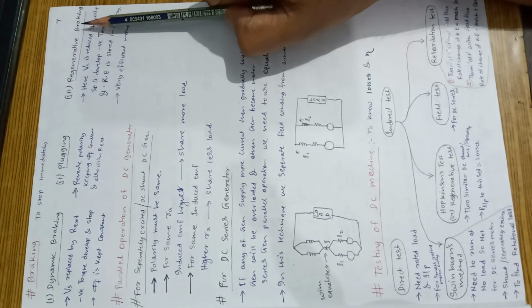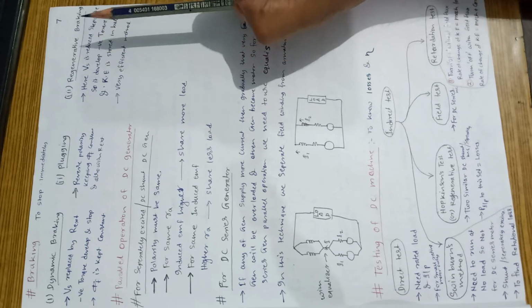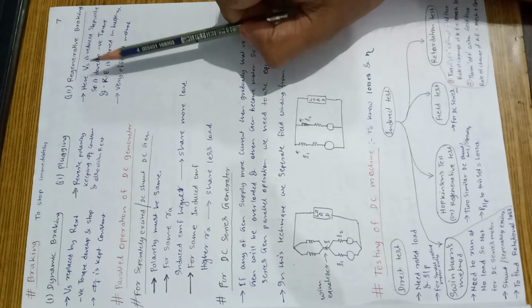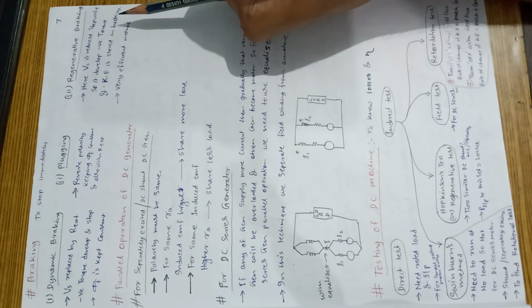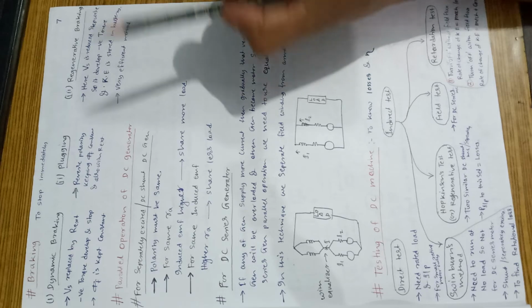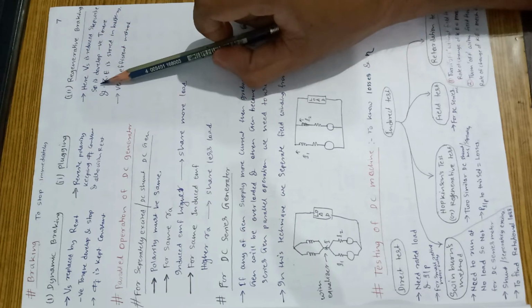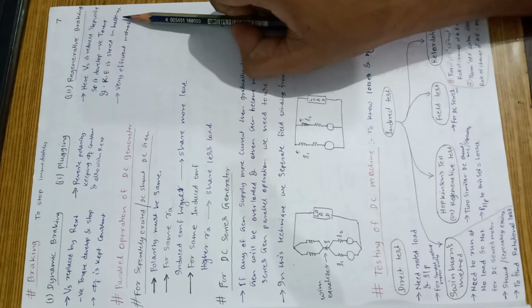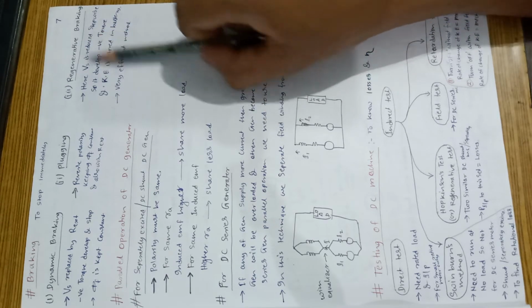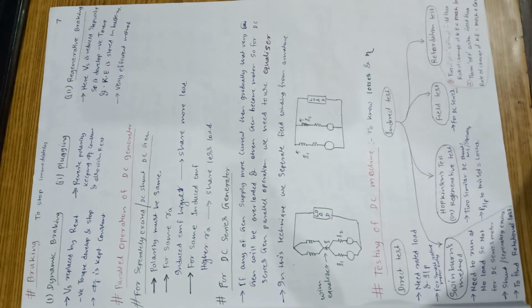It is a very efficient method, because in this we store the kinetic energy in the battery. Here VS is reduced stepwise, so it develops negative torque, and kinetic energy is stored in the battery.